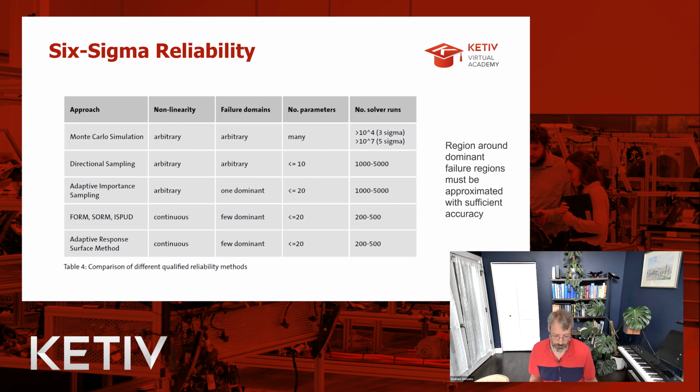I should also mention that you can change the material properties within HFSS as well, create a project variable, and then vary that material variable. And a lot of times in simulations, relative to how well the simulation corresponds to reality, we sometimes don't know the material properties as well as we need to. And so that's another key area of double checking your simulation results to see, is it within the measured realm given XYZ variability of these parameters, dielectric material properties, etc.